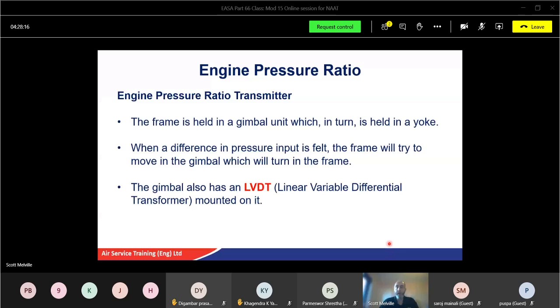Okay, other indicating systems you might come across. Again, oil pressure. This one, a standard oil pressure gauge, goes from 0 to about 150 psi. Minimum pressure is red, and there's the maximum there. Remember, we don't like red because it oxidizes. Green is good, we like to keep it in the green range. 70, 75 psi is pretty much standard for a piston engine, thereabouts. Anything below that, again, remember your LP, especially for the APUs, the LP at 55, 45, and that sort of thing. But a jet engine is a similar sort of setup as well.